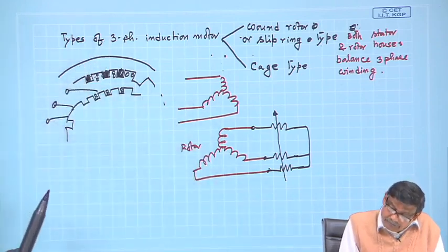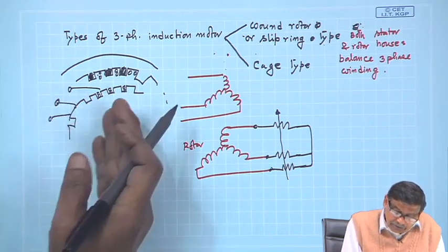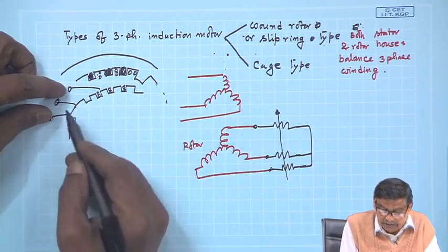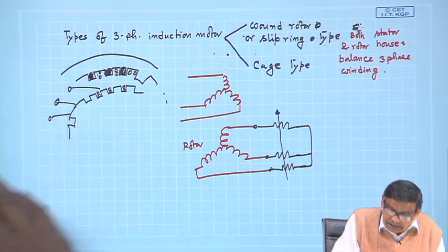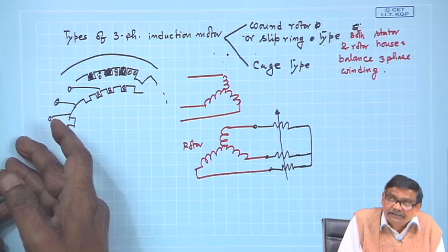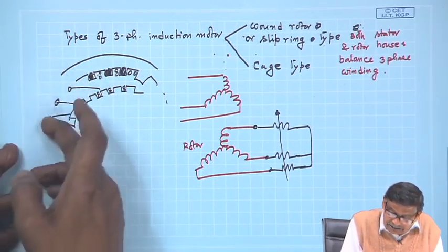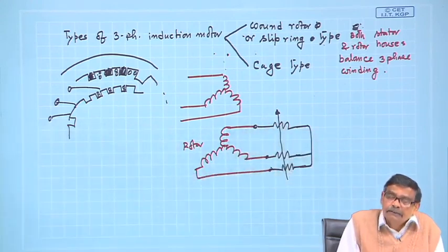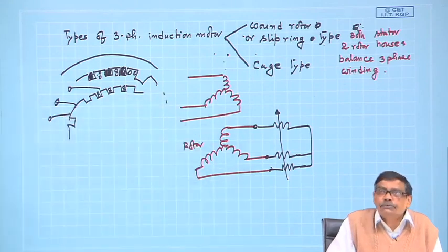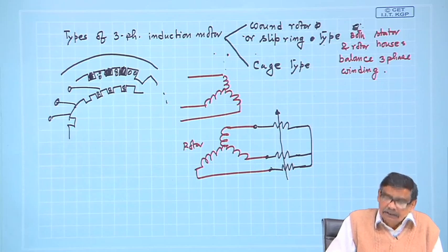Therefore, when it was stationary, if you connect the resistances just like that, these terminals will also be moving, and suppose somebody connects some stationary resistance here on the ground with these 3 terminals, then as the machine rotates, these resistances too will start moving and creating chaos, is it not?